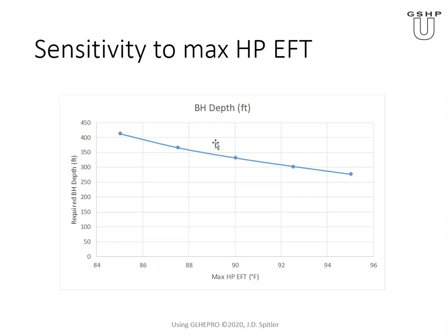If you go the other direction, say down to, what do we go to, 85 right here, we get increased efficiency, but we also need a lot more borehole depth, about 400 feet. So there probably is an economic optimum for every case. But there are other things, like you're going to be limited by what your local drillers or your drilling contractor can do, or what the drilling contractor finds feasible to do, and so on.